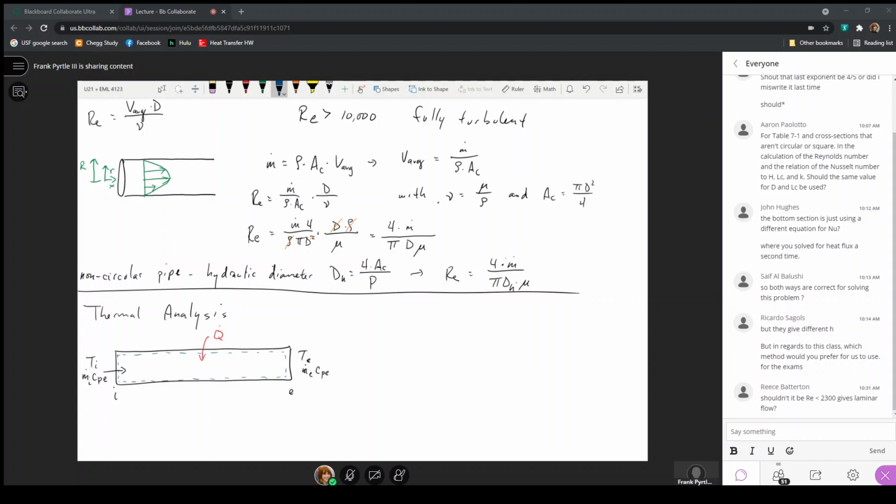If the exit temperature is lower than the inlet temperature, that means a heat transfer was out of the fluid. And here we're talking about the surface, because if I draw the control volume around all the fluid inside the pipe, the fluid is in contact with the pipe at the inner surface of the pipe. So here, I just do an energy balance on the fluid.